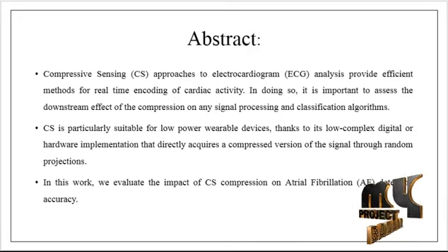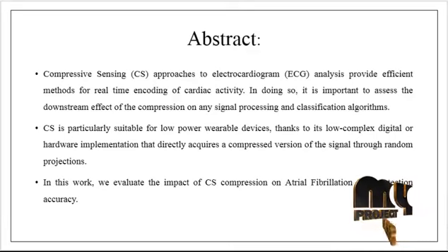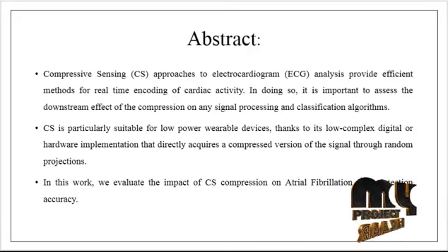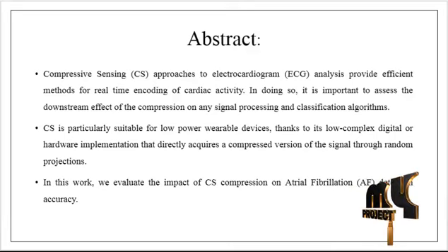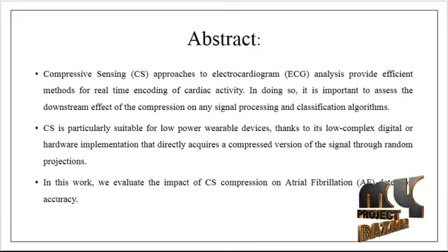algorithm. So compressive sensing is particularly suitable for low power wearable devices, thanks to its low complexity digital or hardware implementation that directly acquires compressive versions of the signals through random projection. In this work, we have evaluated the impact of CS on atrial fibrillation detection accuracy.